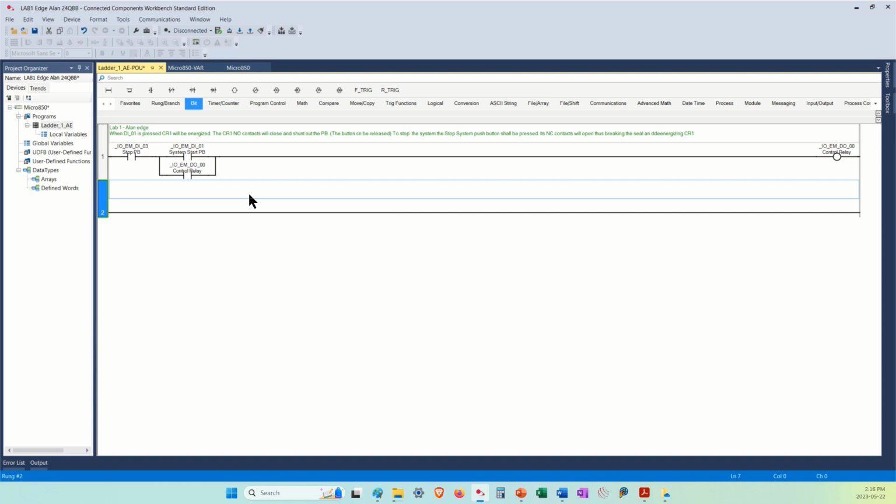So it says I'm to take a new one where the digital output 00 is a normally open direct contact next to the left rail. So they're looking for a normally open contact here. And since I know its address, I'm going to take care of that right now. Output, and they want output 0. There it goes. Then, in series with the first instruction, add another normally open contact.